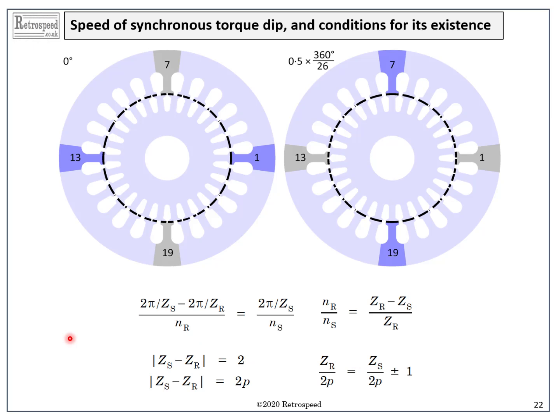The rotor is susceptible to parasitic currents flowing through the laminations, yes, in the axial direction where they interfere with the intended operation of the cage winding. They often bleed current from the bars, and they do this in a patchy way, more in some parts of the rotor than in others. Skewing itself changes the pattern of these so-called parasitic cross-path interbar currents, and on top of that, it modulates the degree of saturation along the length of the machine as well.